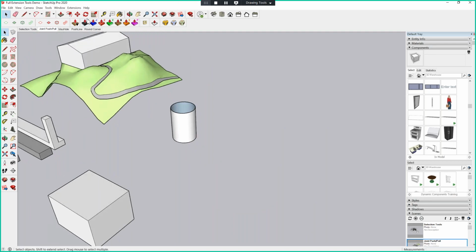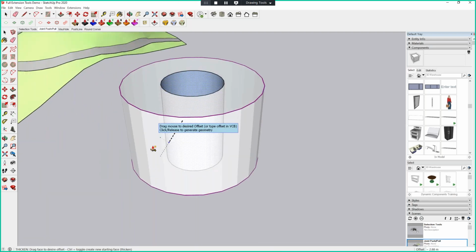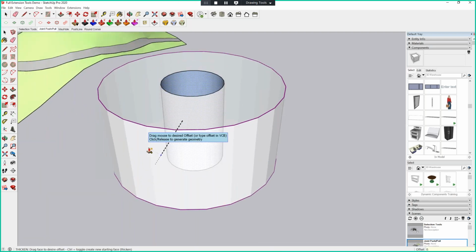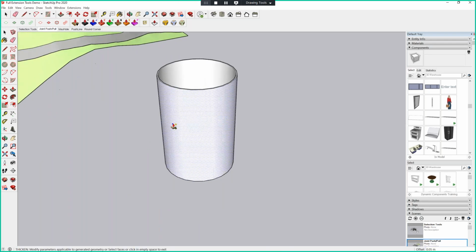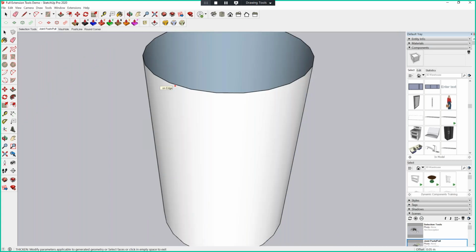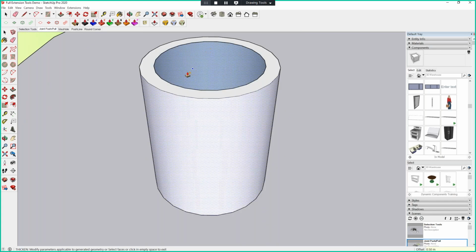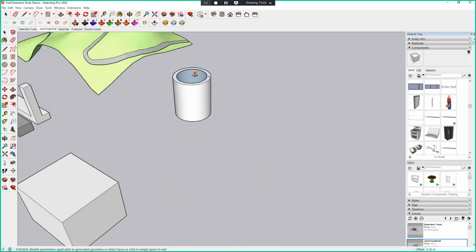So the first one here is an equal sign. It's kind of black in color. This will allow you to thicken a surface. Very simply, it allows you to select this surface and thicken it a specific distance. So if I put 0.045 meters, you can see that it has thickened this surface. Maybe I make it a little bit more prominent, 0.5 meters, for example. So it allows you to thicken that surface when your native tool didn't allow you to do that.